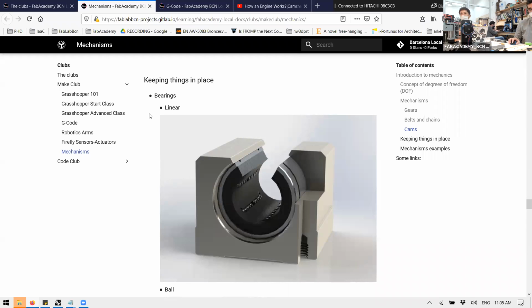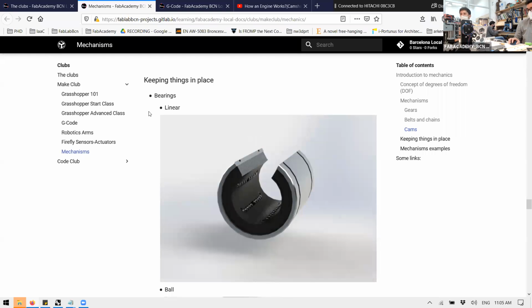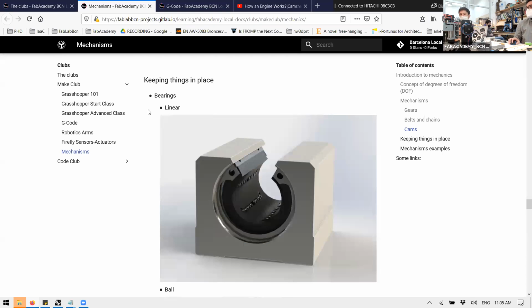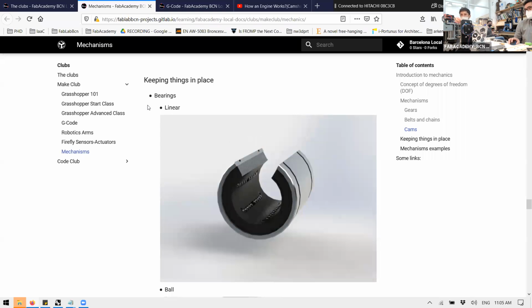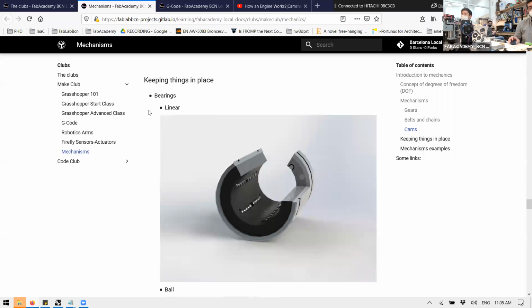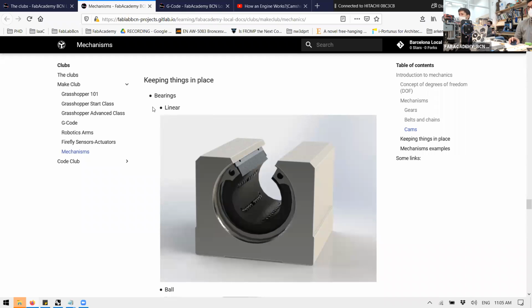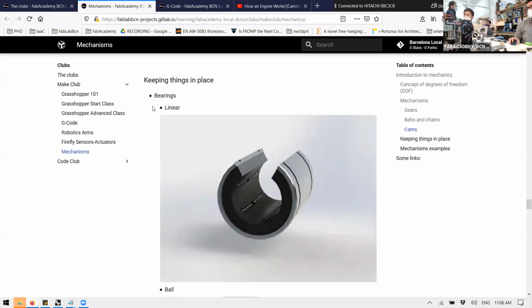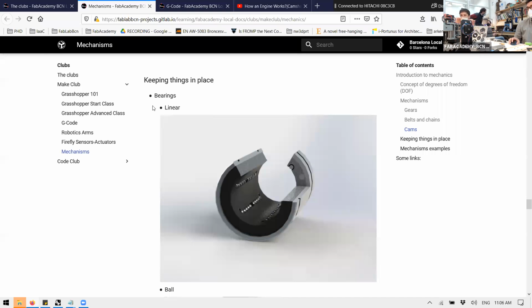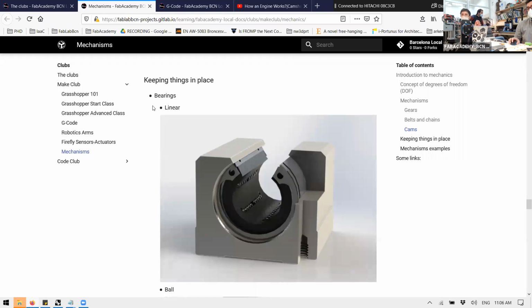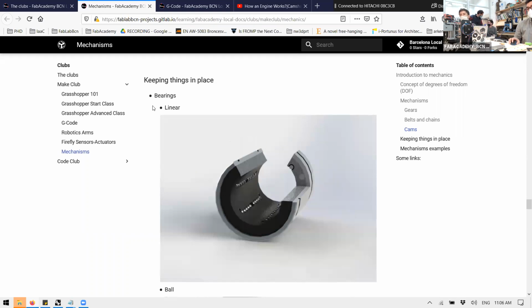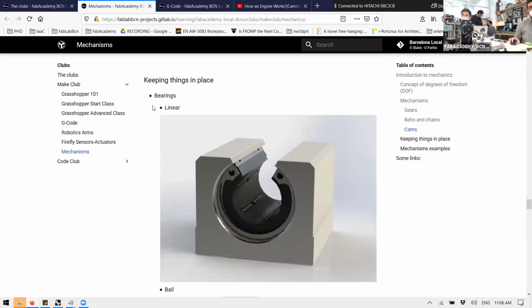At the end, friction is not something that helps you in general, unless you're using, for instance, a belt, like we will see later. That machine doesn't have an actual belt, but some of the machines here use belts for achieving the movement, not timing belts but normal belts, and then you want friction. It's because of the way the mechanism works. But in general, for this type of axes, you don't want it.